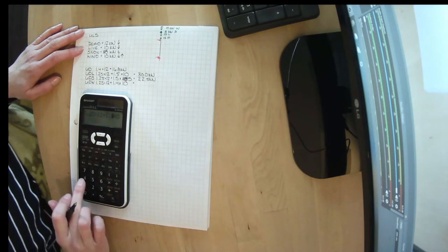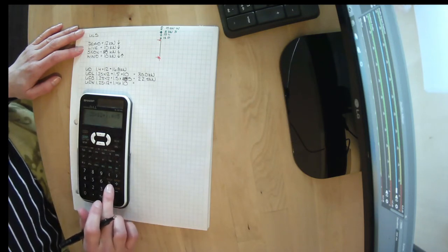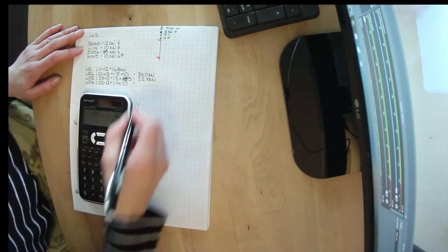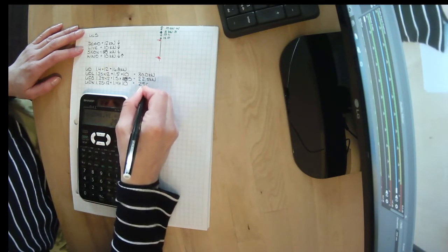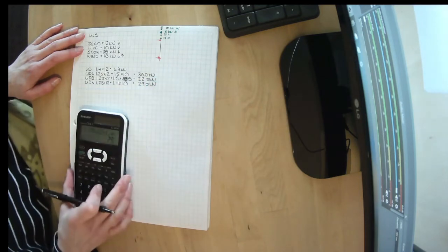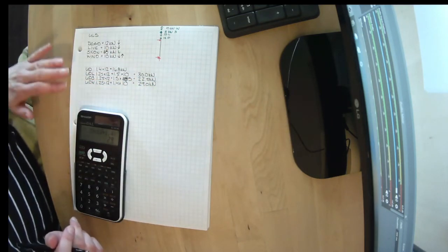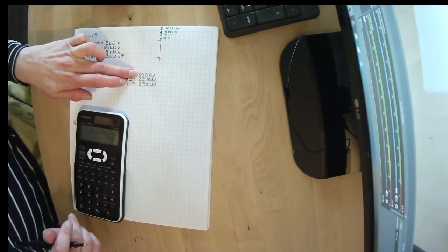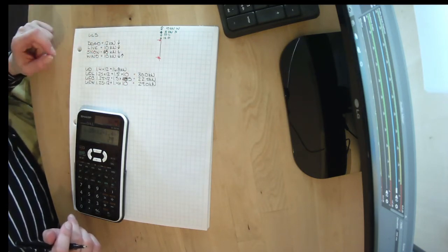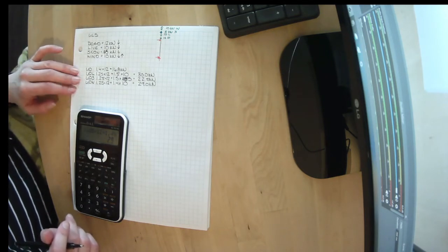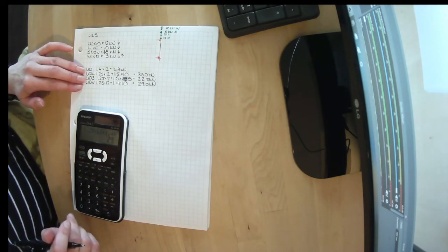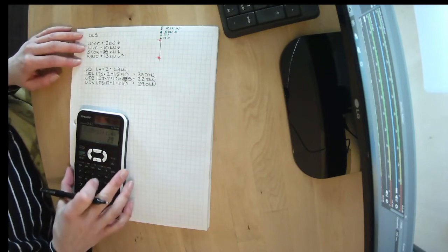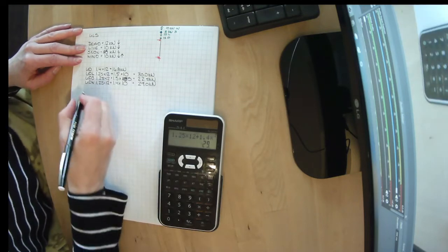And then there was the possibility that it could be dead plus 1.4 times 10 kilonewtons of wind, or 29 kilonewtons. So it looks like so far the worst possible combination of loads our column could see is 30 kilonewtons. But we know there are a few more conditions on these load combinations. These are dead plus the principal loads, but there could be dead plus principal loads plus companion loads. So we have a few more that we need to calculate.